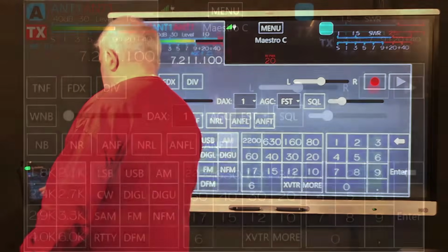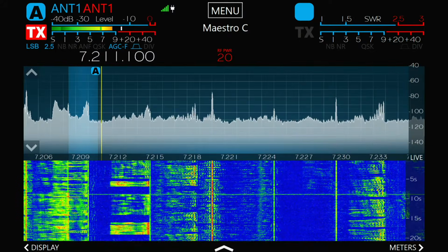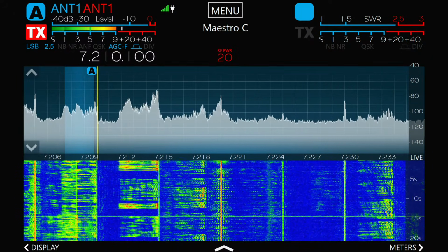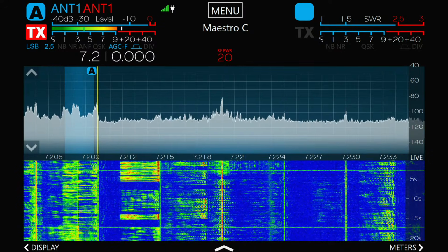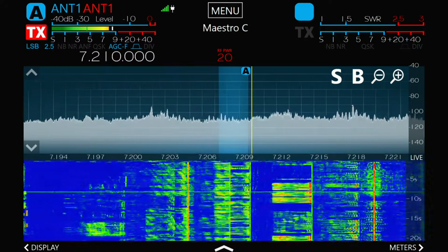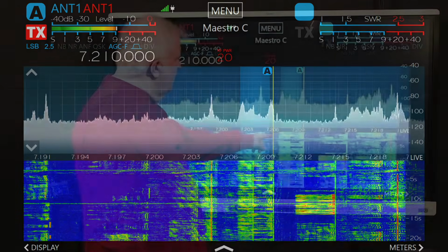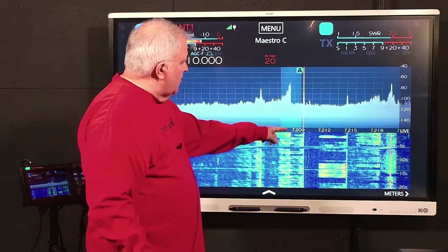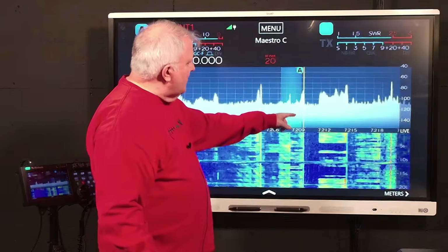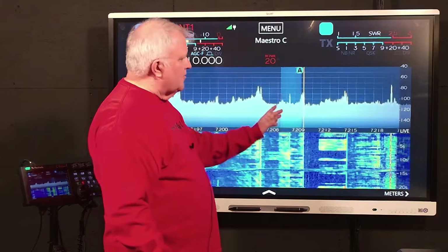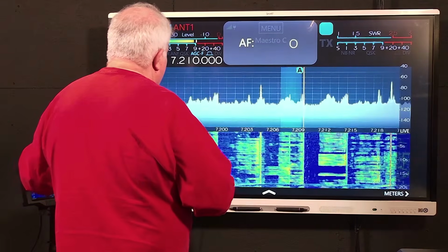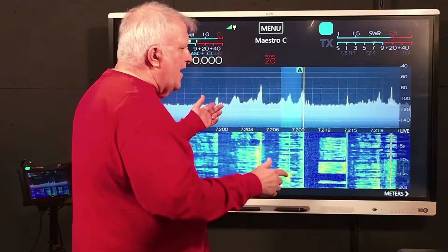But if we take the radio and we go to lower sideband and I retune it, okay, they're speaking Spanish. I can move this over. But here is a lower sideband signal. Actually, two of them. There's one there and there's one there. But we are able to demodulate it. Note there's no upper sideband signal. So this is a single sideband signal, lower sideband. Let me turn it down so that we don't have that competing. So that's on the 40 meter band.